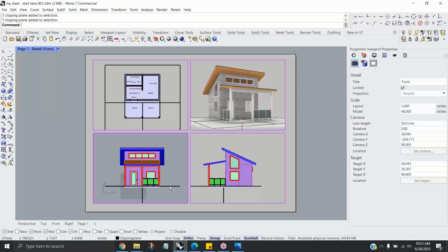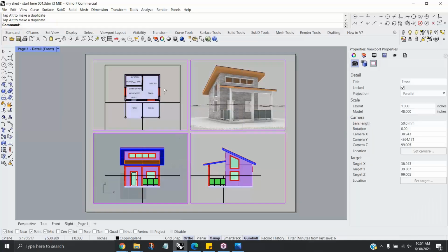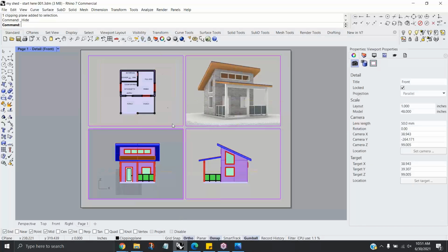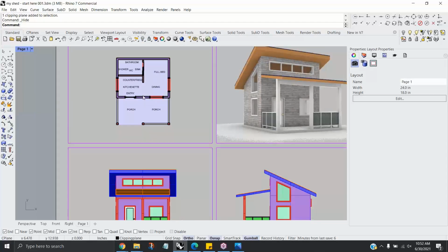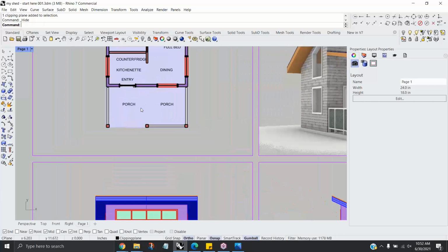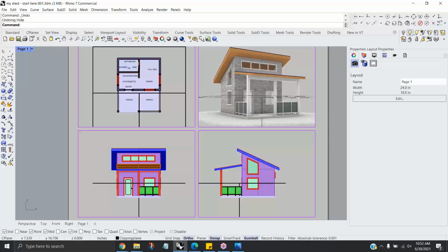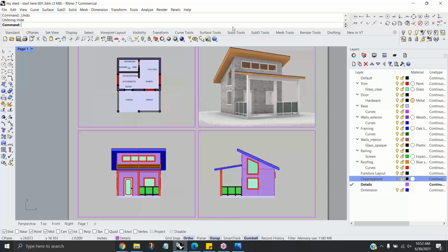I want it on in... So let's grab it here and let's bring it up about 4 feet. I want to make sure and get those windows in there and the door. So anyway, about 4 feet, they say, off the finished floor. And once I have that clipping plane, then I can hide it. And that way I can use it when we're doing the floor plan. And we can keep it. I could also, let me show you the other option. There we go. I can also go to layer and turn it off there, but in order to do that, I need another layer to be current. That works too.